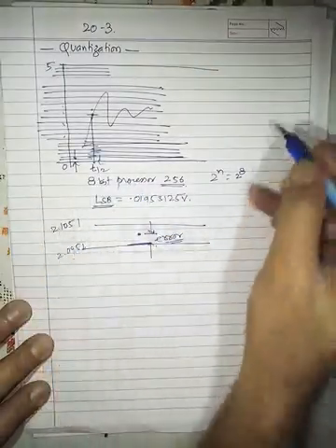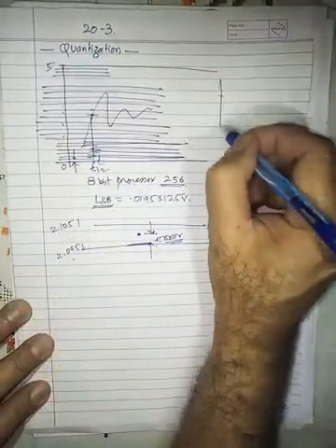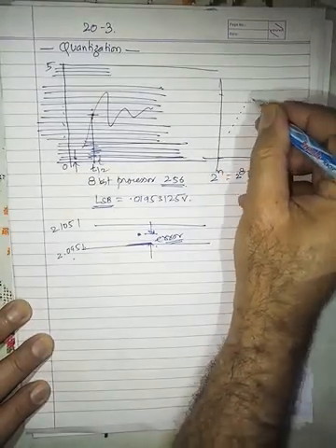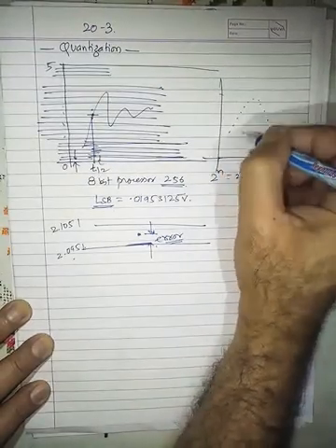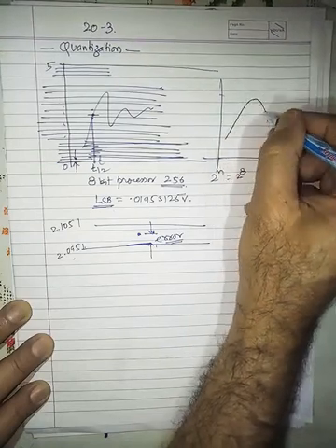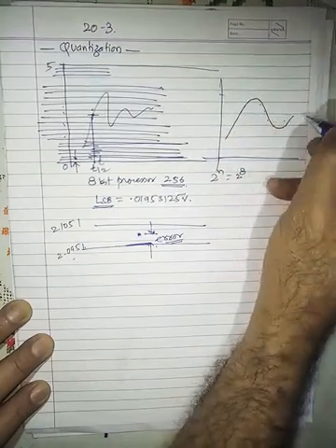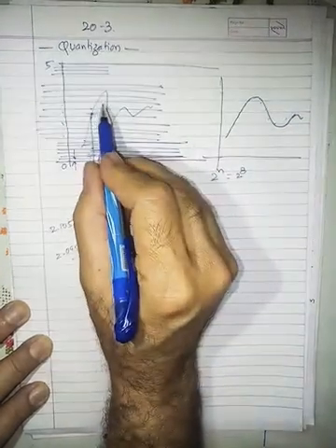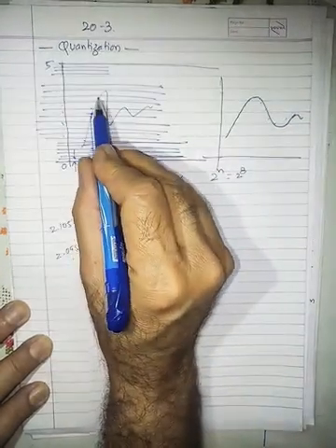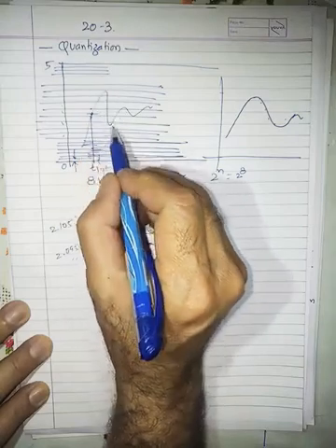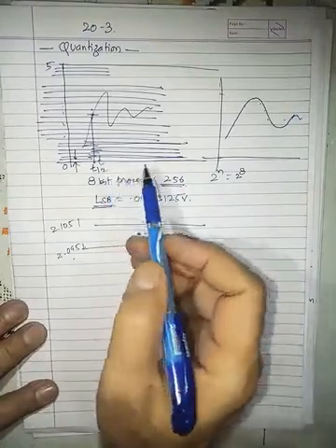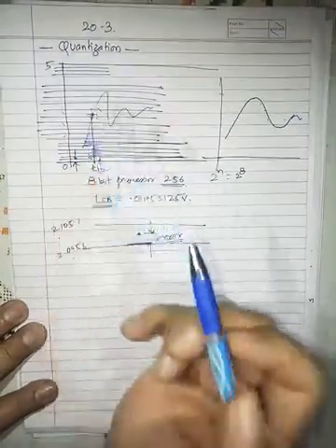And if those levels are called back, and I mark those levels here on this graph, I will get almost the original curve, but not exactly. This will be very similar to this, or very near to this, but not exactly what the signal was before, because some quantization error takes place in this.